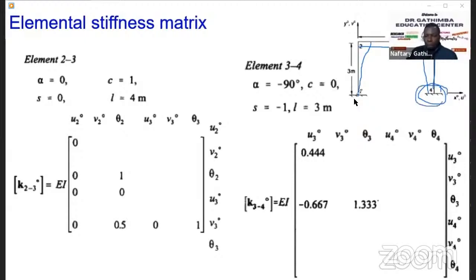If it was pinned, you would need to know how the deformation happens; this you learned from the column, Euler's buckling, and we talked about the effective length of a column. But if this is fixed, then you know there is no rotation there. Okay, so that's that. Quite simple, right?